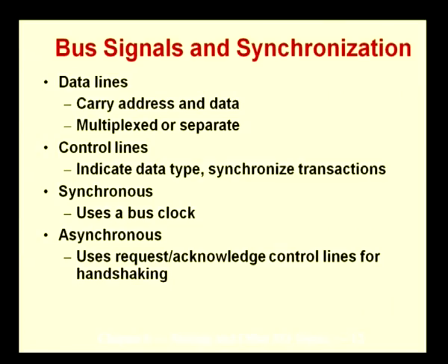So, when we talk of handshaking, it is normally used in the context of an asynchronous transfer, and it is similar to the handshake that we normally do, right, that one person puts out the hand and then another person puts out the hand in response to that. So, you can look at the same thing happening here. One device puts out a request and the other device responds by giving an acknowledgement. So, request and acknowledgement is like doing a handshake. So, which is why it is normally referred to as a handshake set of operations or handshake signals.